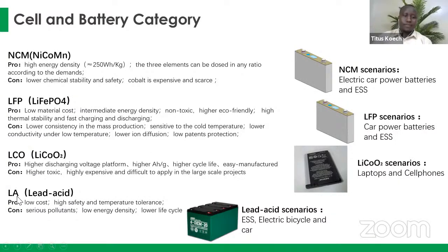I would like to start with lead acid, which, as I said, has been predominant in the market, and it has its own set of advantages and disadvantages, as mentioned on the previous slide. Yes, it's low cost, but the cycle life is quite low, and there is also the energy density and the disposal aspect. That is the key disadvantage.